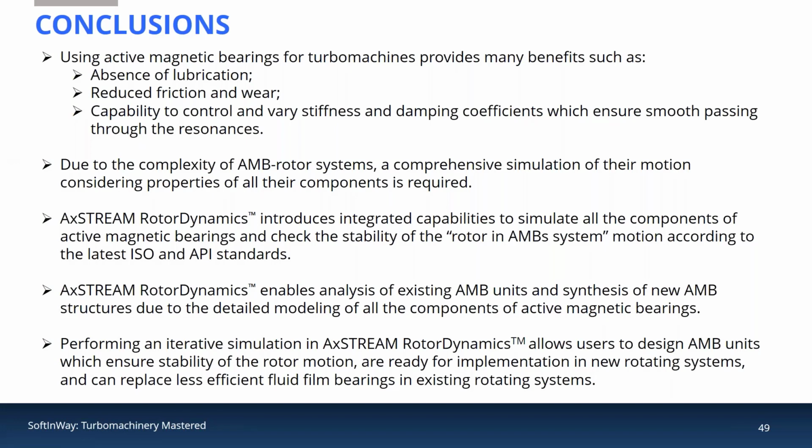All right. Thank you, Vladimir. We did have a bunch of questions come in. The first one that I have here is: as a rule, most bearings, such as fluid film and rolling element, are modeled as spring-damper elements for rotor dynamics analysis. Can we consider active magnetic bearing calculations in the same way?